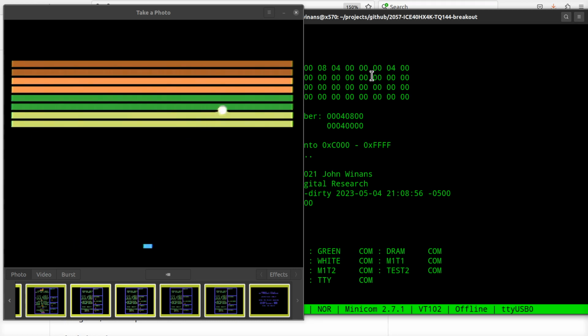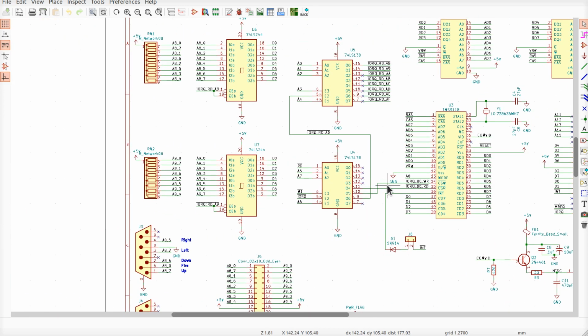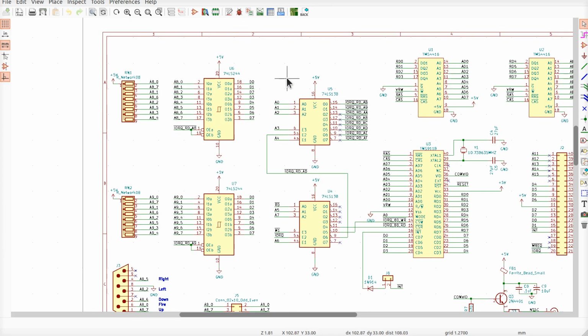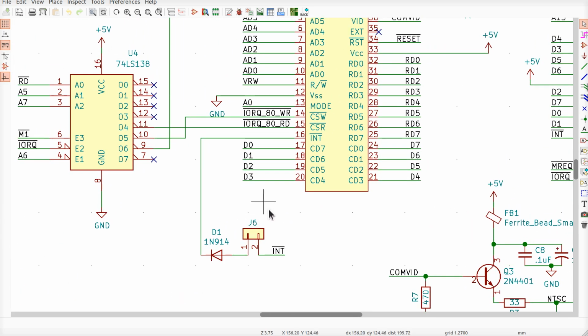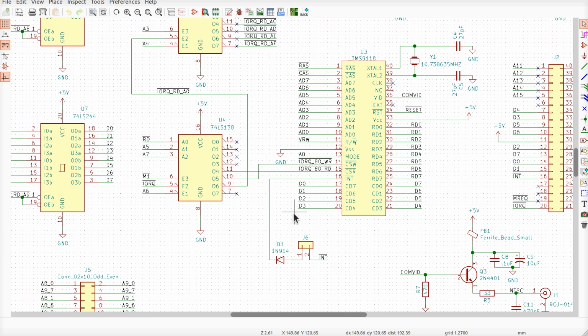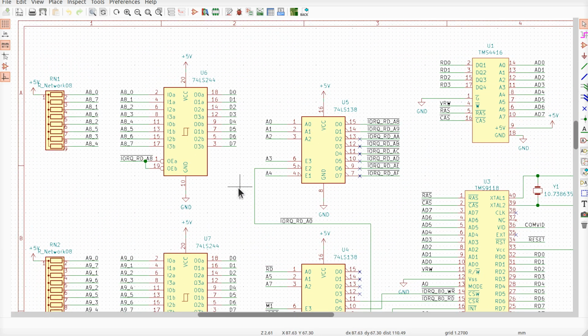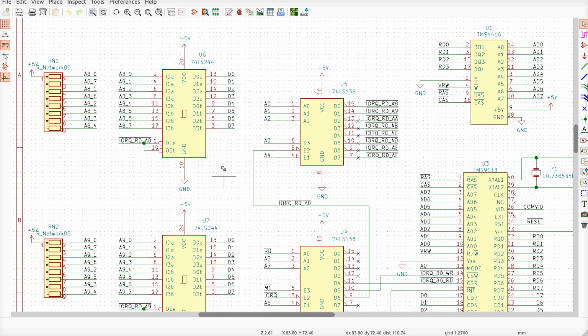And I'm also going to have to now update the schematic, I think, and actually run a track over here to pin 4. I should put a jumper in there so we have the option, just like the interrupt over here. You're going to have the option to run it. I mean, nothing wrong with running mode 1 interrupts. It absolutely will work if you want to do that. Of course, if you run mode 1, you may have trouble if you decide to also have interrupts on from the CTC and or the SIO at the same time, which is why I went ahead and put a jumper here. What I'm going to do is come up with a new rev of this board, not critical, because the bodge wire is real easy to do.